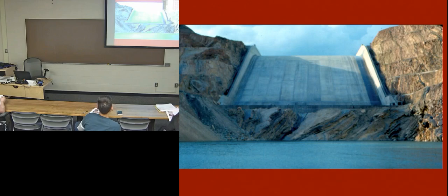So here is what the toe of the service spillway looked like after its first drawdown. And initially, if you remember, we had it nice and manicured up to here. That's about a 100-foot drop. And this is a stilling basin. Now, it was intended to work that way.